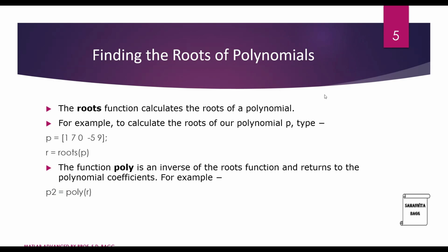Next we will see finding the roots of polynomials. The roots function calculates the roots of a polynomial. For example, to calculate the roots of our polynomial p, type this polynomial first and then you will write down r is equal to roots of p.